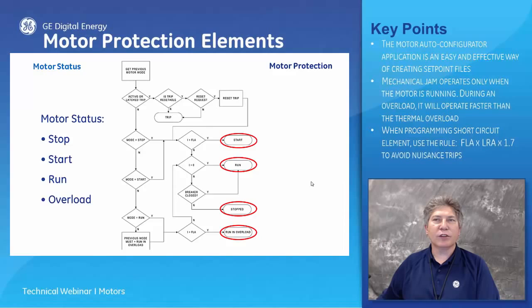As well, the learned values such as the learned starting thermal capacity, learned starting current, and learned acceleration time can be inaccurately calculated. This type of problem can occur when a synchronous motor with a fixed field is run at no load. To overcome this problem, a digital input should be configured to read the status of the breaker and determine whether the motor is stopped or simply idling.